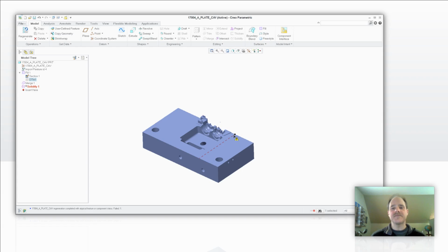So I'm just going to back up my edit here a little bit until it gets past that. Now notice that it went back to having that gray. I'm totally solidified right now. So you can slowly sneak up on this. You can see that there's a value right here. You can change that value accordingly and sneak up until you get right into that little pocket where that offending geometry is. The key here is this.